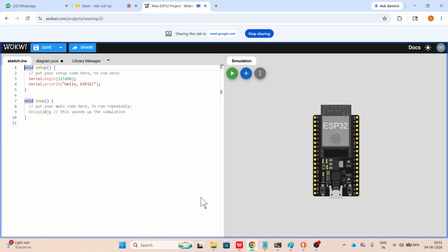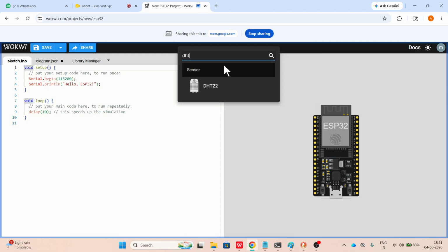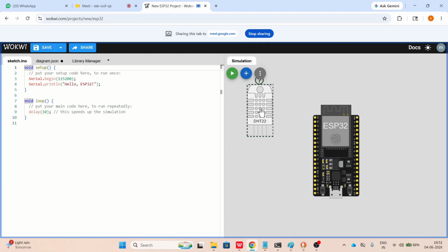Okay. So as I mentioned, next one would be using a DHT22, right? So let's use a DHT22 sensor, because DHT11 is not available. In DHT you have only one sensor, you can see that. So take this. You know that DHT22 has a total of three pins. The fourth one is not a useful pin, not connected. So this one is ground, here you have SDA, and here you have VCC.